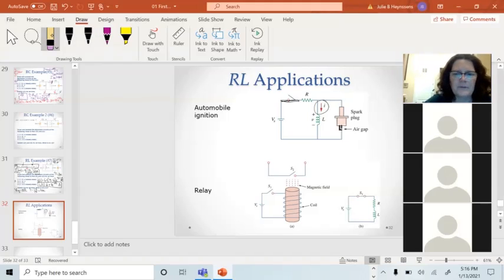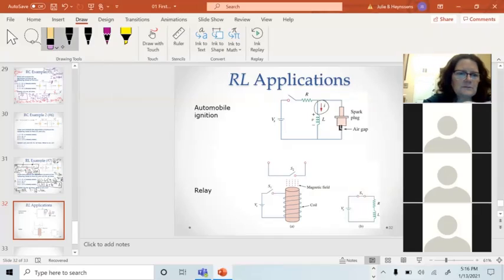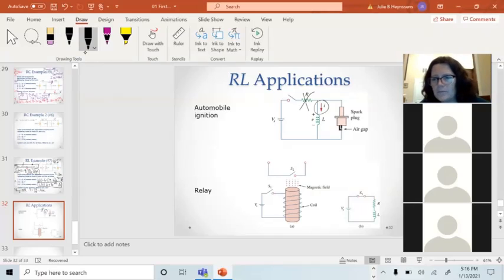The next thing that happens is I throw that switch open. This is dangling, so it no longer has any current going through it. There's only one place for the current to flow, and that's into this open air gap. Turns out air, if you get it up to about 3 kilovolts, will conduct. It will break down and spark and conduct. So the current, since it's forced current coming from an energy source, has no place to go. The voltage is going to rise up high enough to bridge that air gap and cause it to spark.